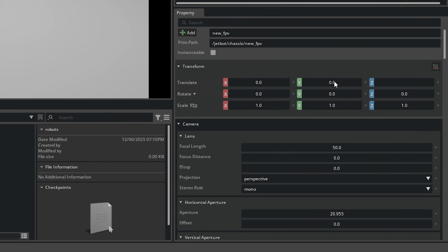On the first row, set the Z value equal to 0.2. On the second row, set the values equal to -60 and -90 for Y and Z respectively. All the other values remain as they were. The first row's Z value controls the height of the camera, while the second row's adjustments ensure the camera is pointing in the same direction we are driving.